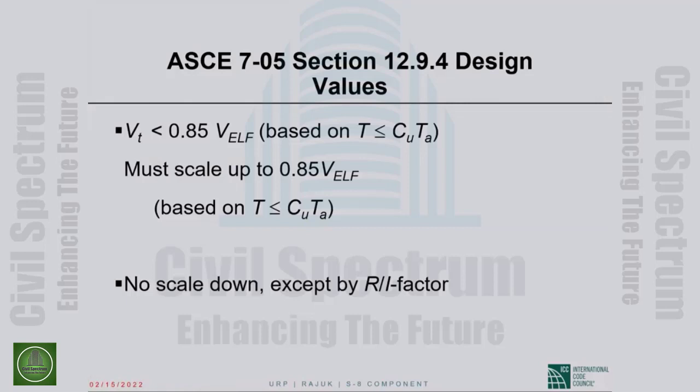Very importantly, there is no scale down of the dynamic base shear. If the dynamic base shear is high compared to the static, you cannot scale it down. There was a time when we used to do it, but no more. And then the R over I modification remains.